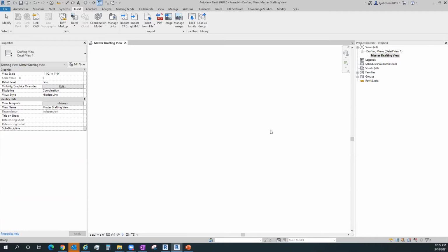It's never something that I continue to build thousands of details in, because when I import and explode, I'm bringing garbage in over and over again that I want to get rid of. So I'll use this as my temporary repository, put the stuff in that I want to see, and once I'm done, I can just throw it away after I've taken the good stuff out of this into another file, which may be for auditing or a master file.